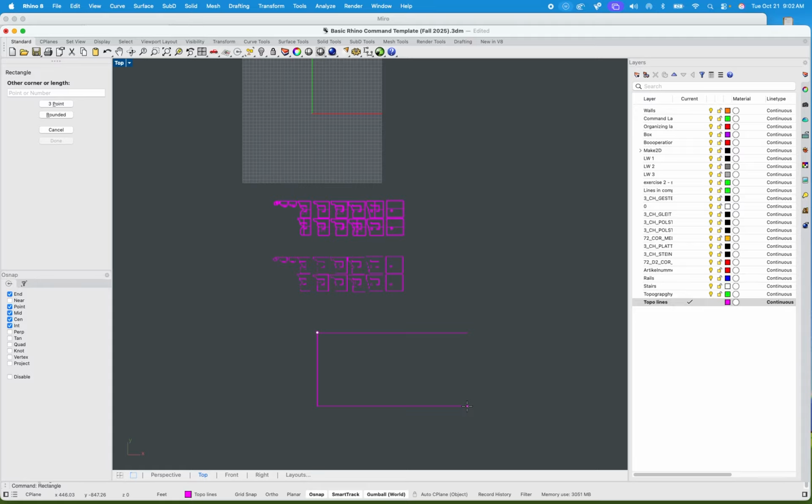If it's outside the area, it won't cut, right? So it literally has to be in that area, or it won't even cut the whole line. Say there's a tiny millimeter sticking outside of the border, and that whole line is connected to the inside of the bed. It'll just not cut the entire line because a small millimeter was outside of the proportion. That's definitely important, right? Because you'll cut your entire thing and go, why didn't it cut some of these lines? And it looks like it is exactly at the border. And if it's not, it won't cut.